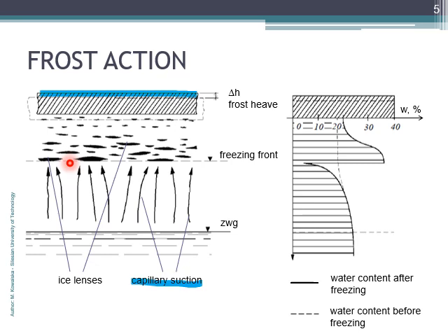The soil is therefore likely to be in some unstable state. Look at the picture on the right. We are talking about soils that contain some amount of fines. As you know, the amount of water, so the water content of such a soil, is a very important geotechnical parameter because it tells you about the soil consistency. And you know that the more water the soil contains, the softer it becomes.